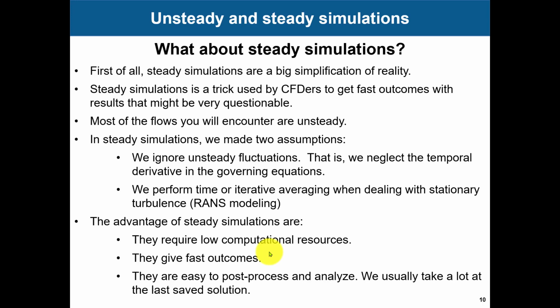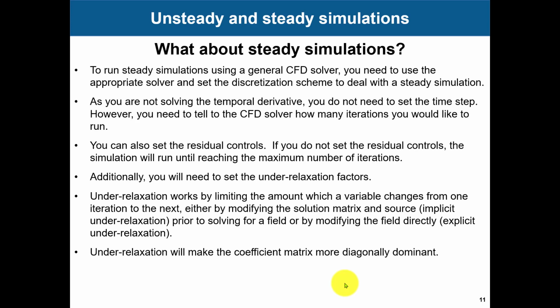So they are really fast, but you need to know when to use them. And also they are very easy to post-process and analyze. In a steady simulation, you need to save information, monitors, time analysis, time series, whatever. Here, just open the last file and that's all. You know that everything has been averaged. Okay, very easy to post-process.